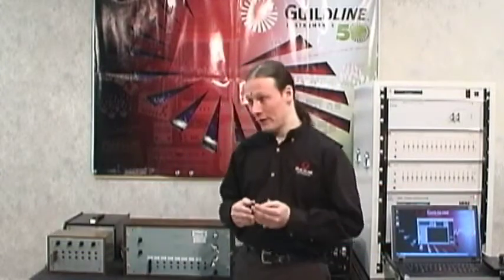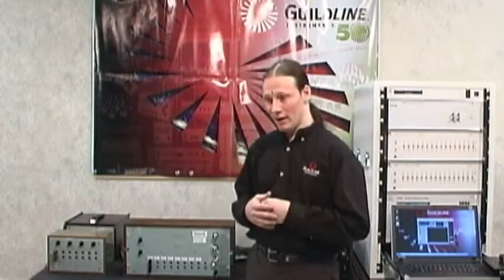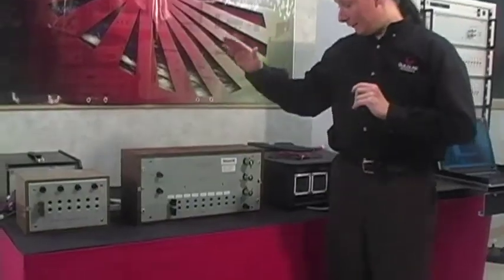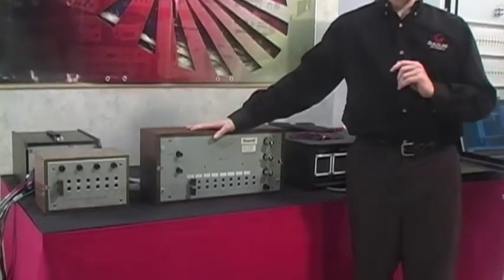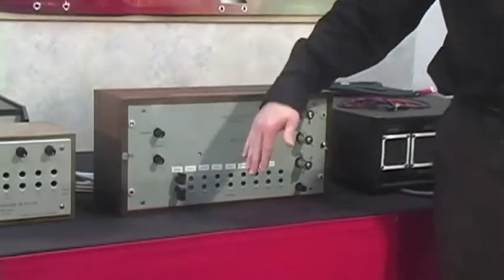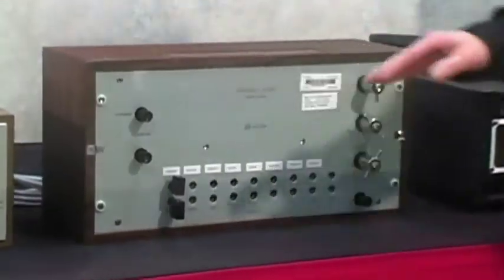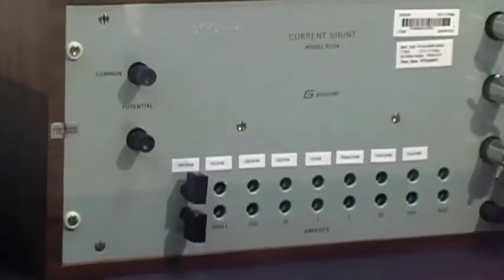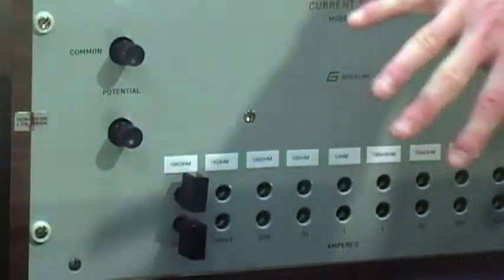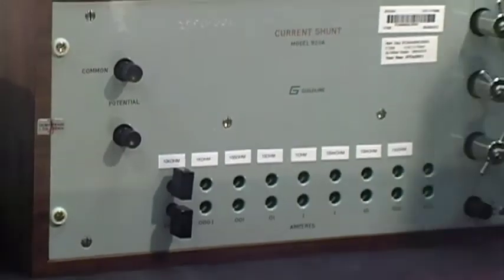We're going to go through a utility in the software that is designed to help automate and aid the process of calibrating a multi-value shunt. For people who are not familiar with the multi-value shunt, things like Guildline 9211 or 9711, it is a shunt that can have very specific values for measuring different current ranges. Essentially you connect your current through here and you get your potential pickup here.